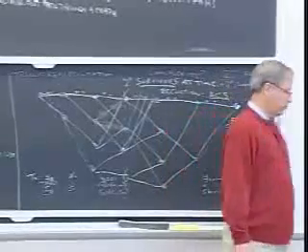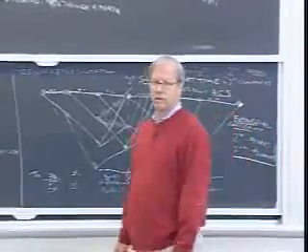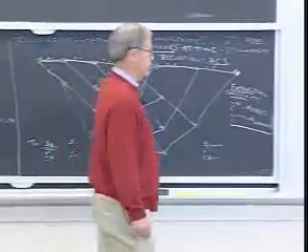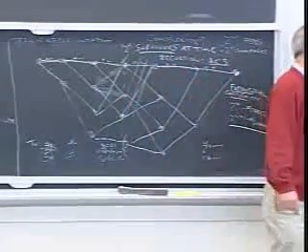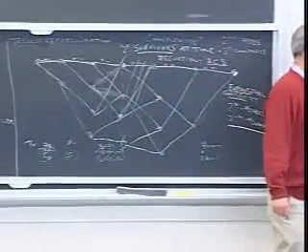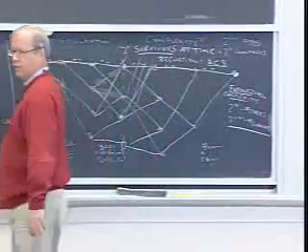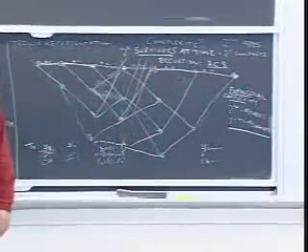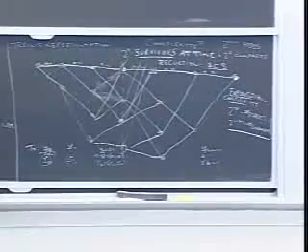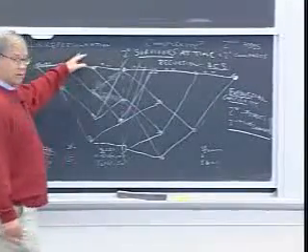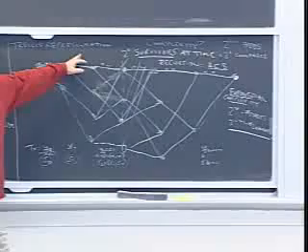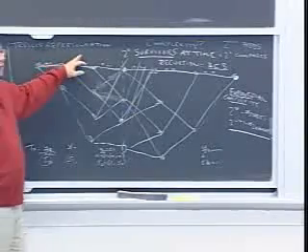But when we're talking about moderate complexity decoders, these have proved to be the most effective and have become the standard moderate complexity decoder. The advantage is that we can do true maximum likelihood decoding on a sequence basis, using soft decisions, using whatever reliability information the channel has, as long as it's memoryless.